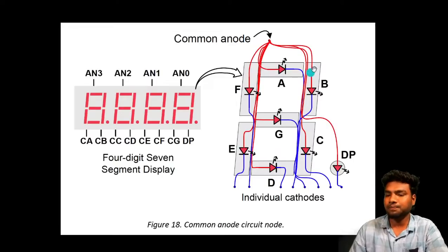And then it has a binary. If you want to display 1, you just have to give 0 here, 0 0 0, b equals 0. Like the second bit in binary, b and c you must give 0. It means the remaining bits have to be 1, so that only then you can see the 1 in your seven segment. So let's see in this session how to write the code for multiplexing.